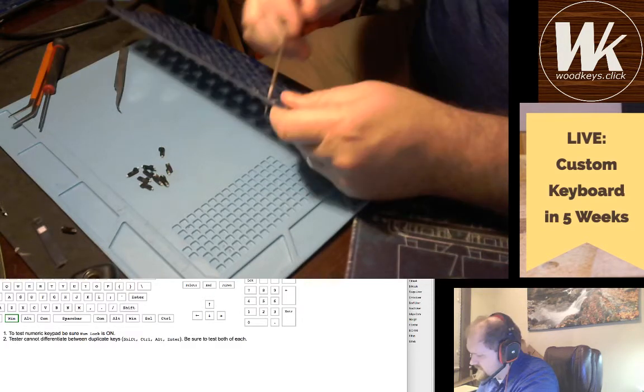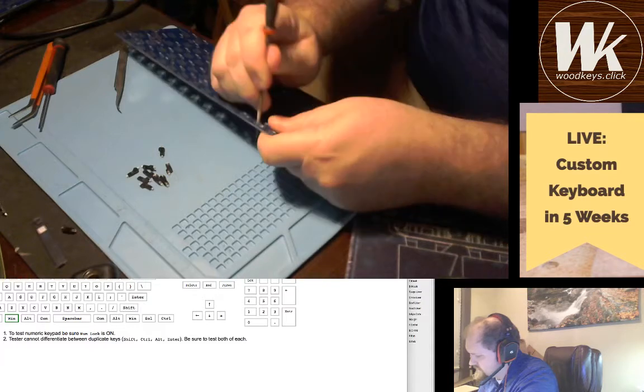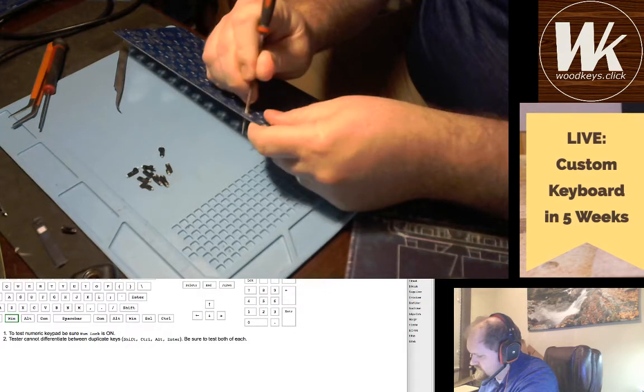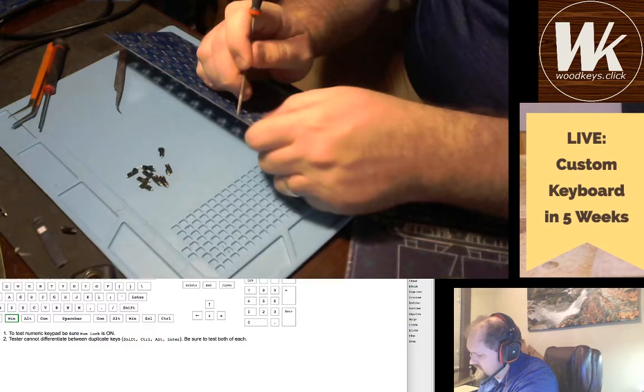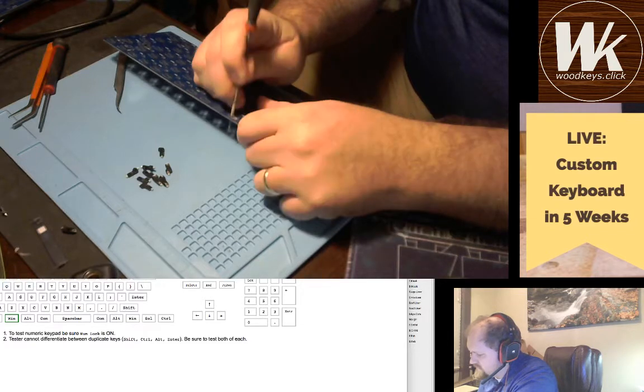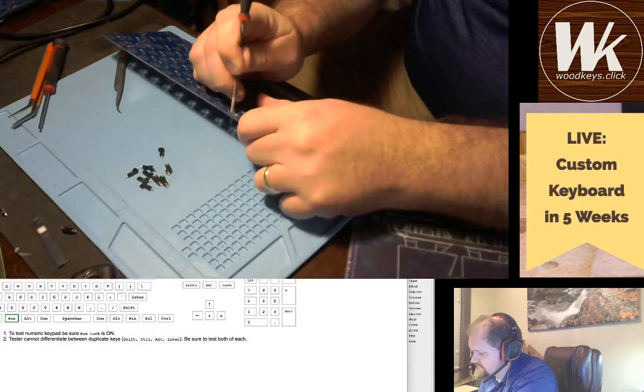Maybe do it like that. I think sometimes the manufacturers only have certain drill sizes. So if you specify a drill size, they're going to pick the one that's closest. They have a lot, but maybe they don't have this particular size.